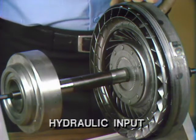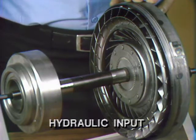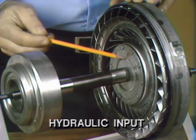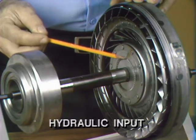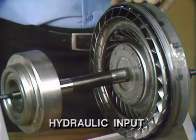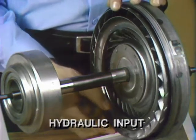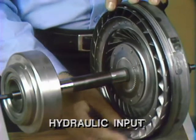Hydraulic input can happen two ways: all hydraulic or in split torque, hydraulic and mechanical. This is because the sun gear for the splitter planetary unit is splined into the hub of the turbine, and the turbine shaft is splined into the sun gear. With the turbine and shaft in place, we can see what happens in 100% hydraulic input.